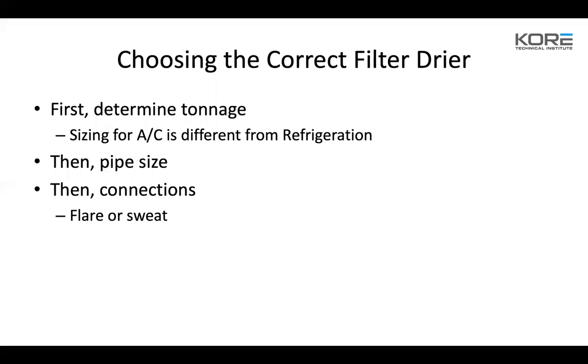Most of the time in the service side, you're swapping out. So like I said, if you're ever changing out a filter dryer, always go up in size, never go down. That'll keep you safe. And then, like I said, adjust the charge accordingly. If you have a receiver in there, you might not have to adjust the charge, but if you're dealing with a sealed system critical charge with no receiver, then you're going to need to make sure you adjust the charge accordingly.